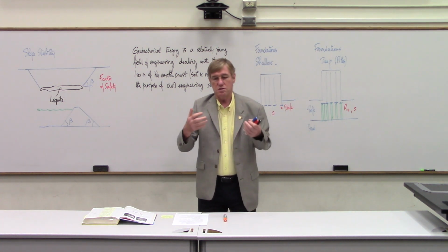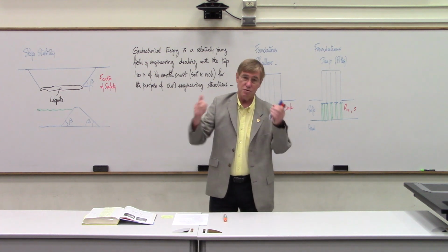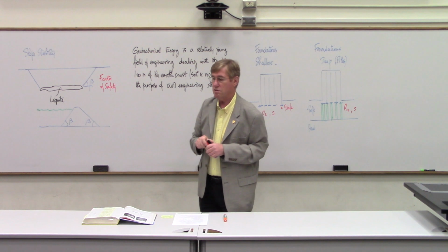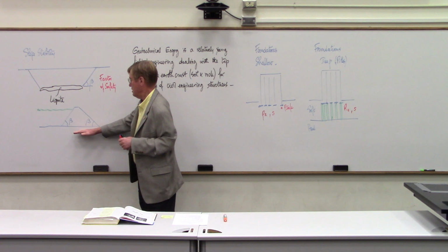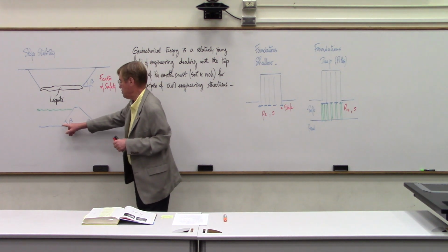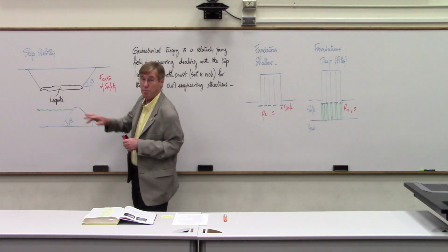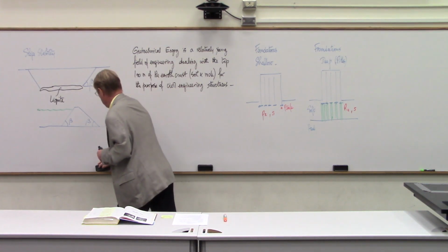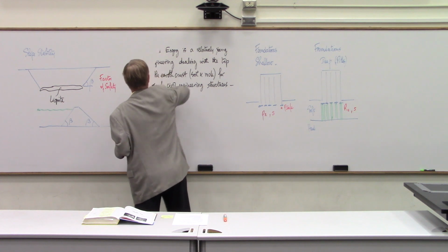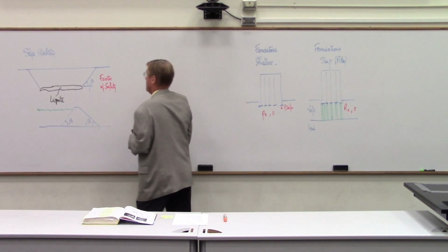Earth dams just sit there, they're heavy, the weight is what prevents them from sliding, and they retain the water pressure that's exerted behind them due to the fact that they're heavy. And of course, in the earth dam, you've got to make sure the water doesn't come underneath or through the dam, because this is soil, and soils are pervious. But the slope stability is another issue when it comes to geotechnical engineering.